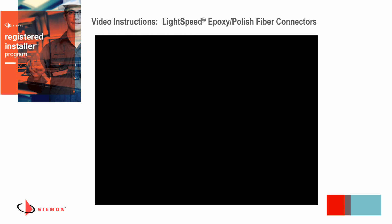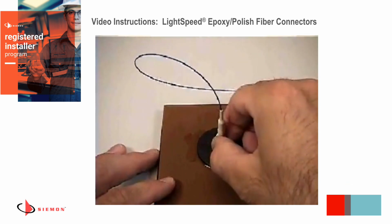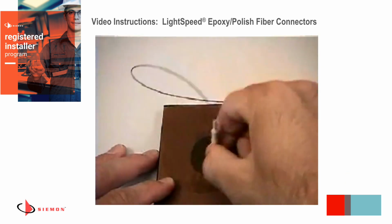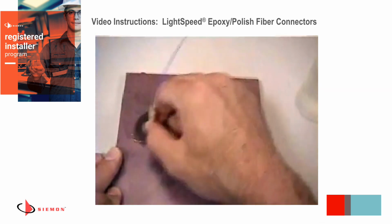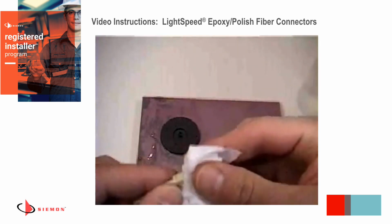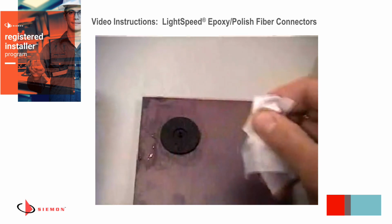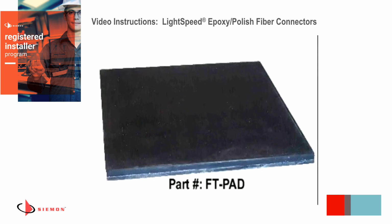This procedure requires the bronze-colored 6-micron recovery film, part number FT-PF6. This film is sold separately and not included in the consumables kit. Using the 6-micron recovery film, perform a pad polish step identical to the initial one, then continue as normal starting with the pink 3-micron film. Be sure to clean between steps to prevent transfer of debris between films. For larger jobs, consider purchasing additional polishing pads and pucks to minimize setup and cleaning time.